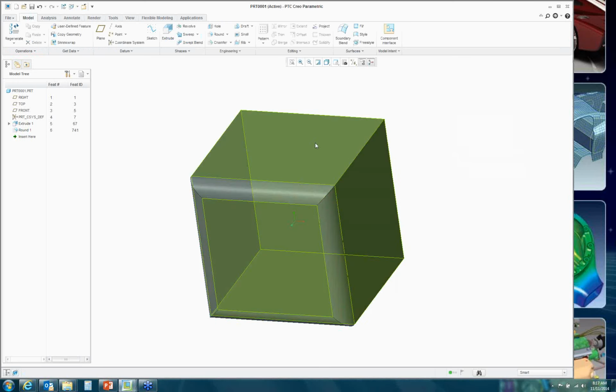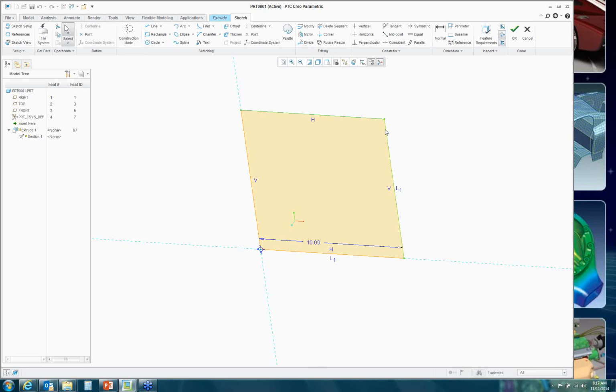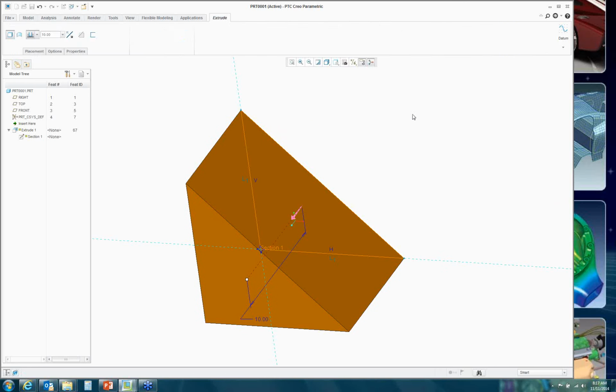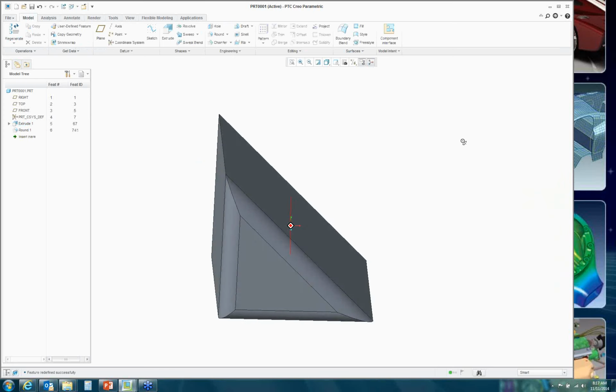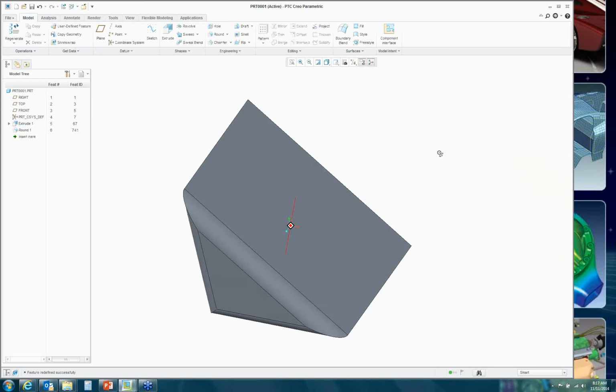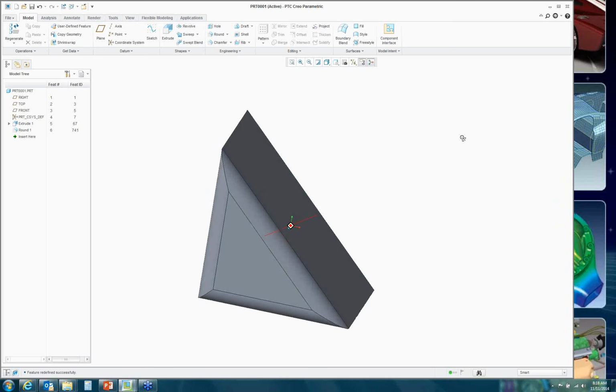we're good to go. Again, if I take that feature and edit its definition and edit the internal sketch, and we'll delete these 2 pieces of geometry, recreate some geometry, I'm still going to get a round at the end of that feature because that's what I told it to do. I said collect all of the edges at that surface using intent selection. Okay.